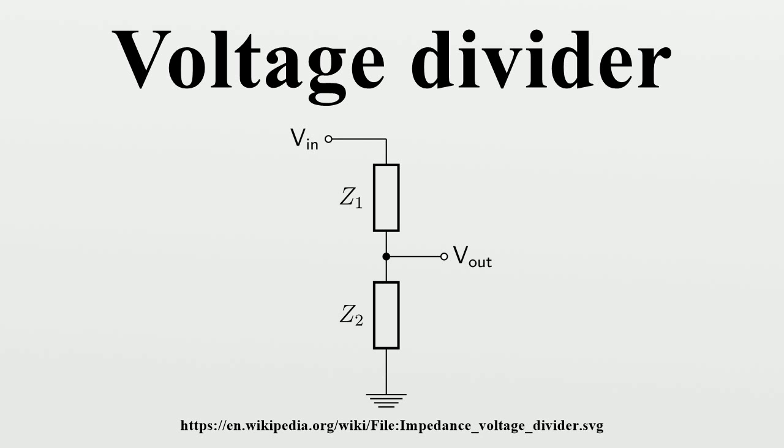The product tau equals RC is called the time constant of the circuit. The ratio then depends on frequency, in this case decreasing as frequency increases. This circuit is, in fact, a basic low-pass filter. The ratio contains an imaginary number, and actually contains both the amplitude and phase shift information of the filter. To extract just the amplitude ratio, calculate the magnitude of the ratio, that is,